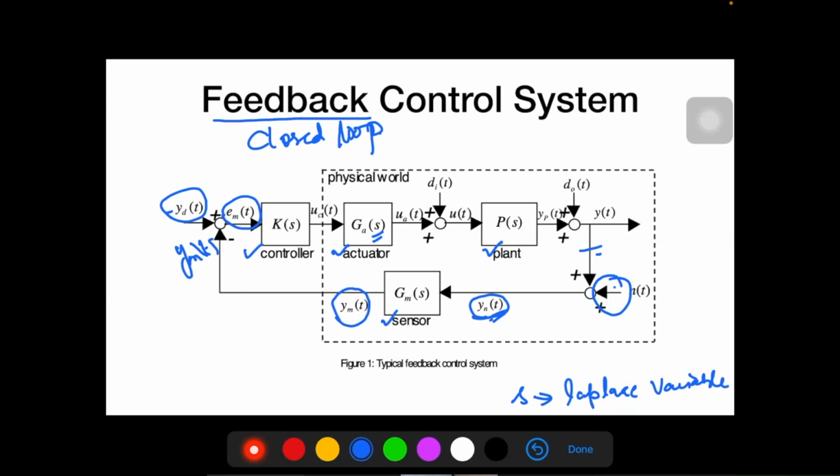Now the controller accepts the input as well as the value from the feedback. So both are being fed back into the system. The purpose of this feedback is for the error E to be minimized. E we usually call epsilon, the error rate. That error rate has to be minimized; only for that do we use the feedback system. Once the error rate approaches zero, which never fully happens, but approaches a very minimal value, then you will always have a perfect system.